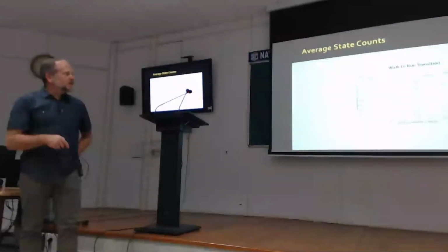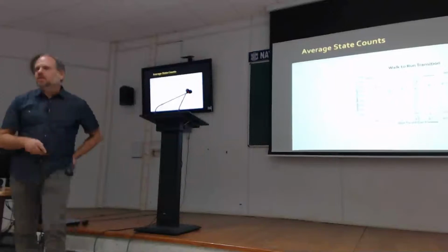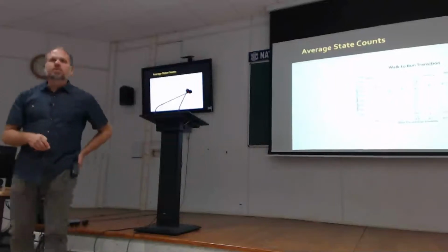It's a little bit light, sorry, on the screens, it's hard to see. But in the transition from walking to running, interestingly, we found some variety in the length of states between those. But when the transition occurs, they all have this inflection point, and then it goes flat afterwards. So we looked at this spot and said there might be something here that can build into a heuristic to make a rules-based switching command.